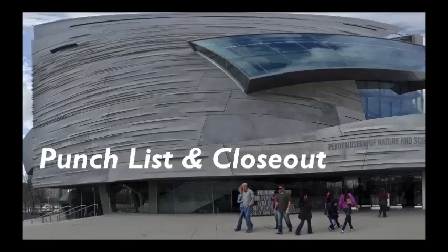A punch list is where the contractor will go through, and typically the owner and the architect will also walk through, and they'll look at all the individual things that they need to fix before they will consider the building done. So maybe they painted the walls and then they installed some equipment, and the person installing the equipment scraped the wall. So they might put a little sticker or something. I mean, not the one that sticks permanently, but some little marker that could be removed so that they know that's a punch list item.